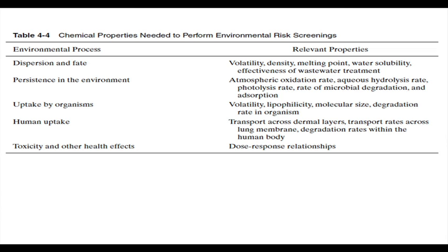And one term you hear a lot when we talk about air pollution issues is particulate matter, PM, PM10, PM2.5. PM10 means any particle less than 10 micron, 2.5 means particle less than or equal to 2.5 micron. So, molecular size, the size of the particle, is important.